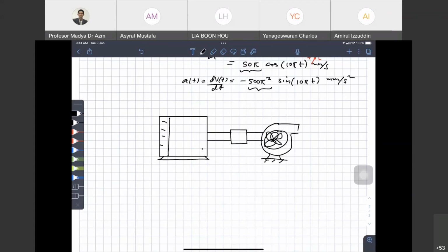Okay, so here also we can determine the conditions of the coupling. So this one is coupling. If we take the data here, and then we take the data here, and you have the phase which is 180-degree difference, it means you have a bad coupling here.